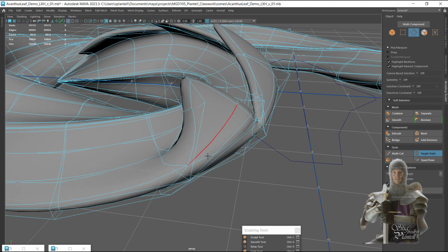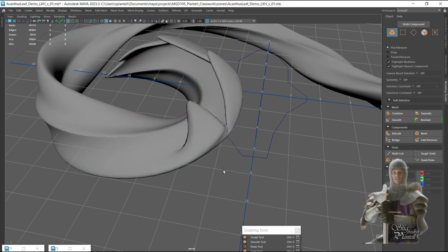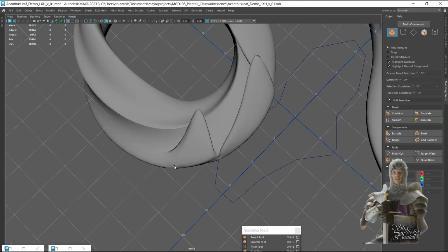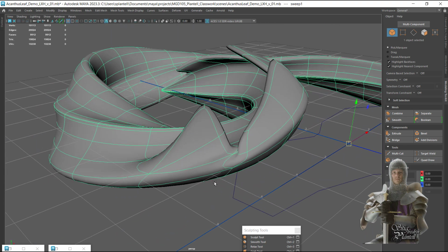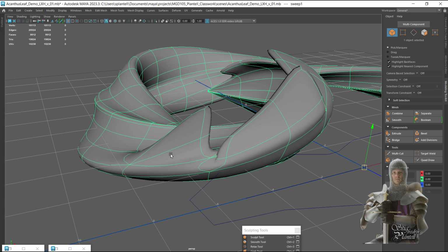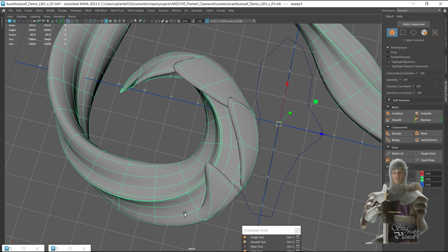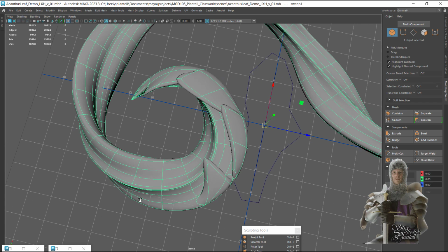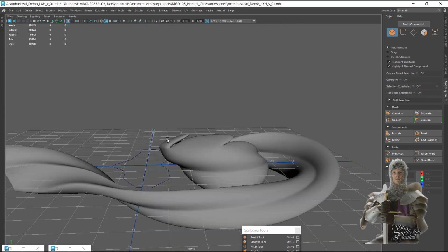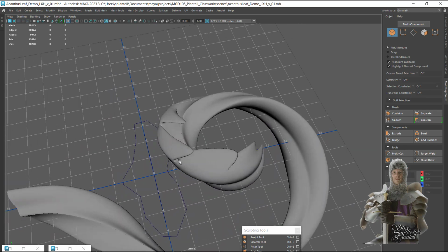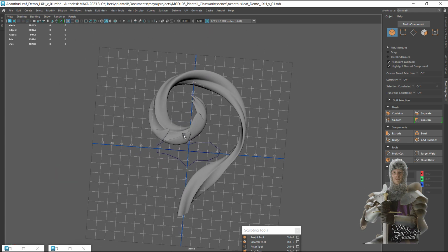Let's click off of it. It thinks I hit, so it has a clean and smooth end. I think for that one we'll merge that and let that triangle be. At least it's terminating, and we know that the form is the best practice for geometry. Mostly we want quads, but sometimes you have to break away from that. Look how neat that looks. Let's see if we can bring that kind of thing to the rest.